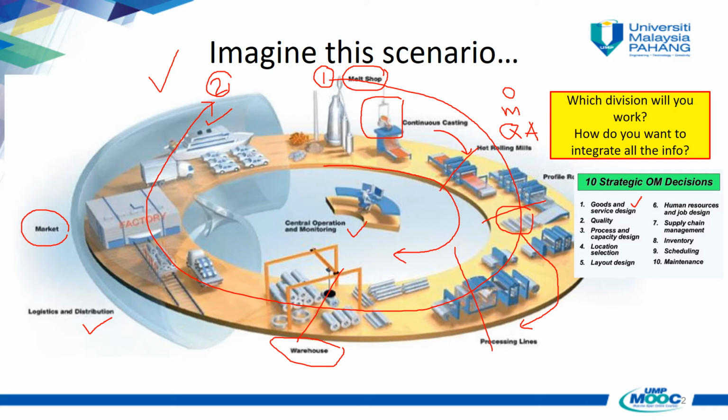And secondly, for each of these stations, you need a decision on quality. What is the temperature that you require? What is your pressure? How much is good, how much is bad? What is the range of your processing parameters? What is your upper control limit, lower control limit? Can your process be repeated? Those we call quality.